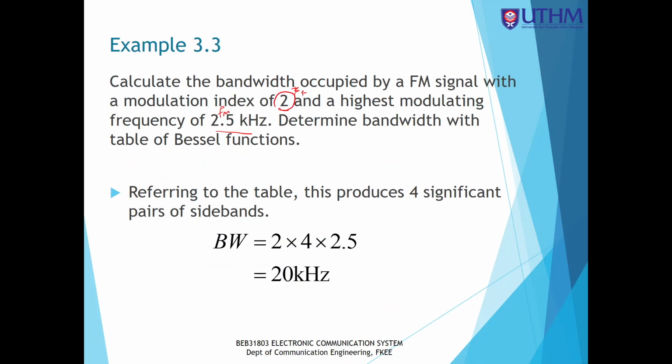That means 2 times 4 times the modulating signal frequency 2.5 kilohertz. So we're gonna get the answer, which is 20 kilohertz.